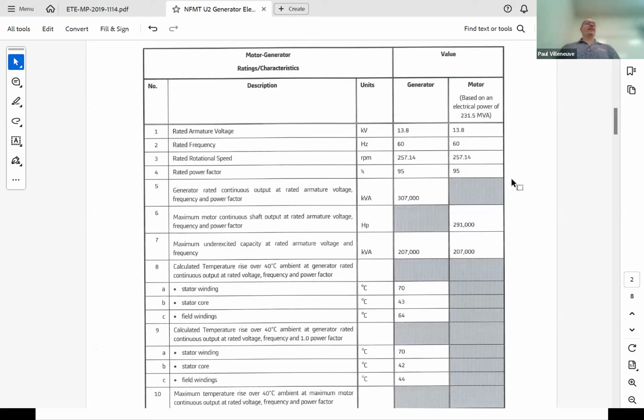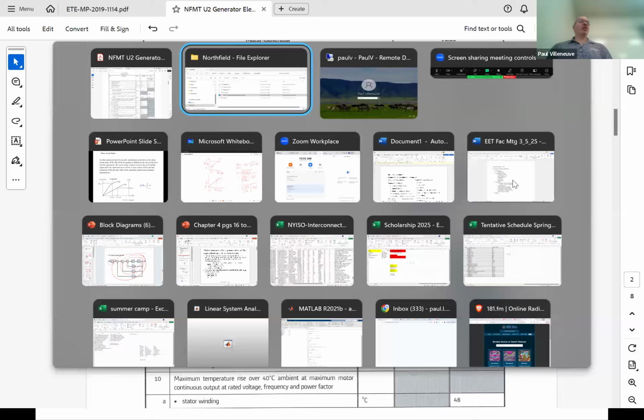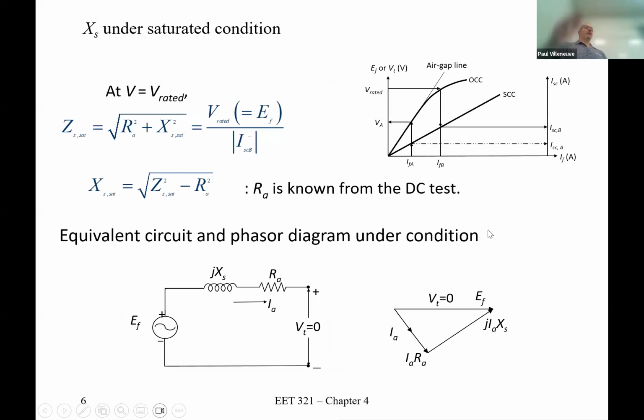Not a clue how to do that? It's the wrestling part with it. But it literally is just ignore any value of RA and go through our calculations that we had over here. Just find consistent field currents for it and then divide the voltage by the current. That's going to give you a ratio. Or if you multiply by the 13.8 with the square root of 3 and then divide by the 12,844 amps, you're actually going to get something in ohms.